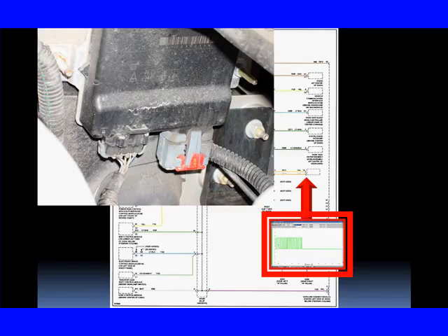Now, there are some very specific procedures for verifying that that signal is the same signal that's on the bus. What we do, if we think we've got an opening, and we get a status that says we cannot communicate with a particular module, what's the status? That's when we take our scan tool and try to communicate. Some software calls it pinging.